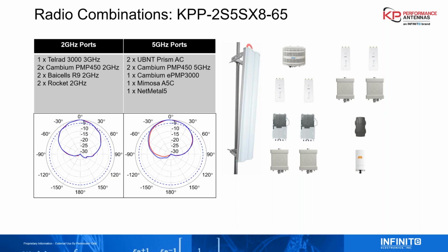But really, it's going to be trial and error, in order to make sure you get it right. But you're going to need some type of spacing, and it's always going to depend on that radio's filtering ability, out of band filtering, or out of channel filtering. So that's, I'd say 10 megahertz, and it's definitely possible.